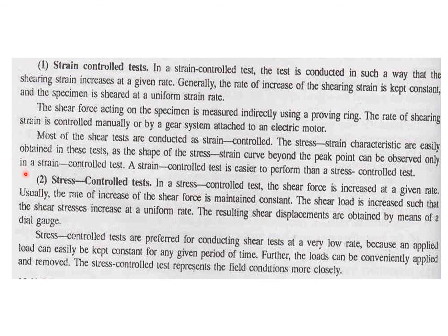Now look at the stress control test. In a stress control test, the shear force is increased at a given rate. Usually, the rate of increase of the shear force is maintained constant. The shear load is increased such that the shear stresses increase at a uniform rate. The resulting shear displacements are obtained by means of a dial gauge.